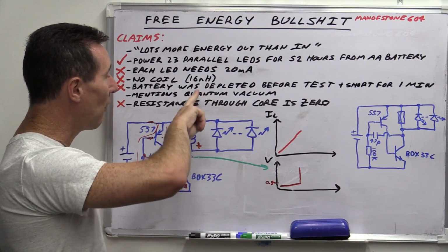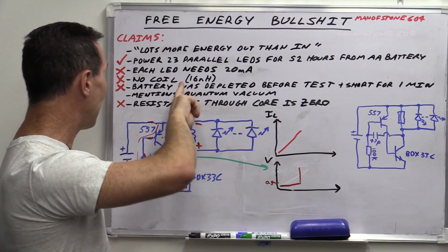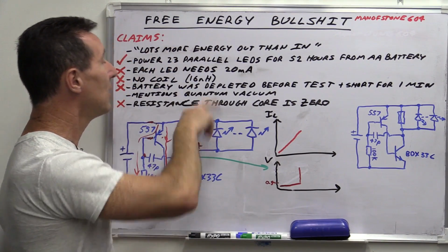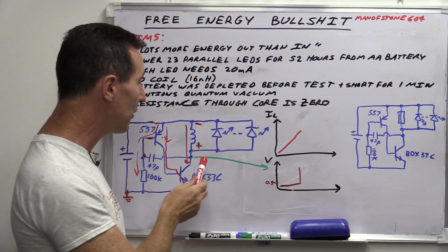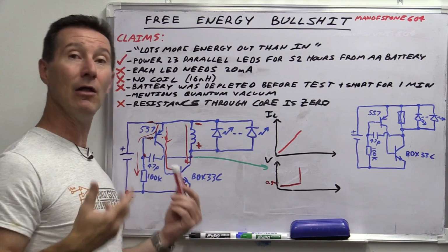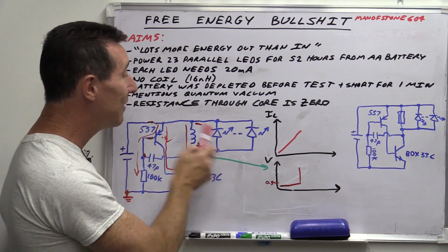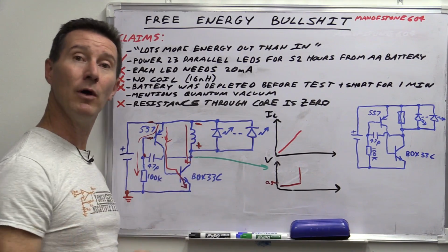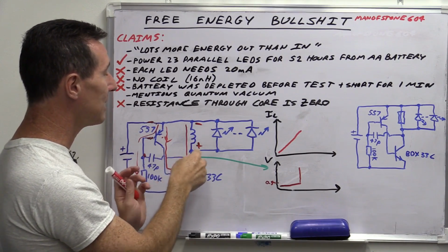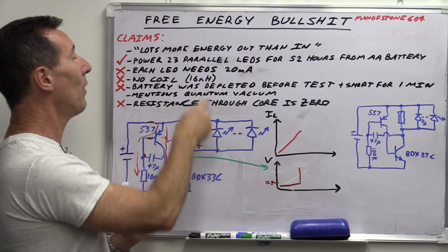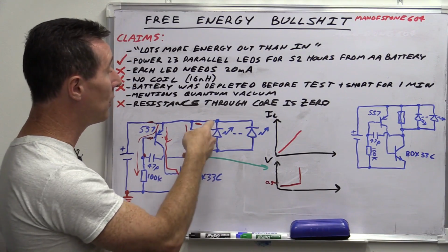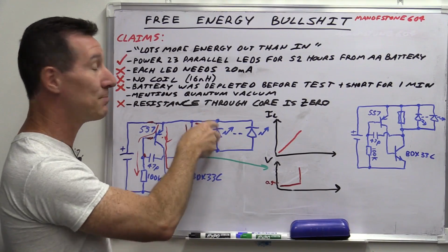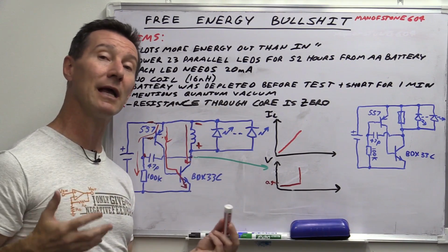That swings the voltage at this point here up above our battery voltage, which is sitting at our 1.2 volts average or whatever it is. Swings it up to a very large value at this particular point. How large? Well, it's actually going to be clamped with our diode, because if you have a look, our diode is actually backwards. If you thought about this conventionally and didn't know that the voltage at this point went above the rail, then you would think that they've installed the diode back to front. Oh, no, they haven't. The reason it's back to front like that is just like a relay coil.